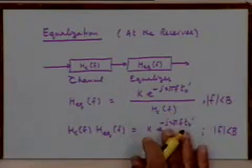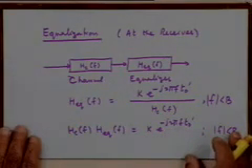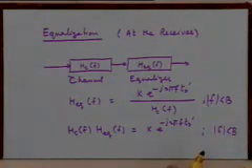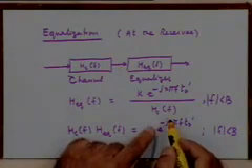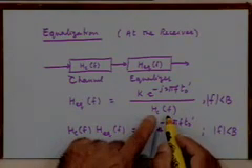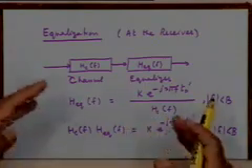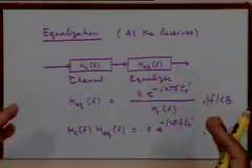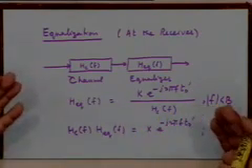To learn the channel characteristics so that you can implement an equalizer filter of this kind is a non-trivial job. The second problem that may arise, even if you knew the channel transfer function, is due to the fact that we have ignored another very important component present in the channel: noise.